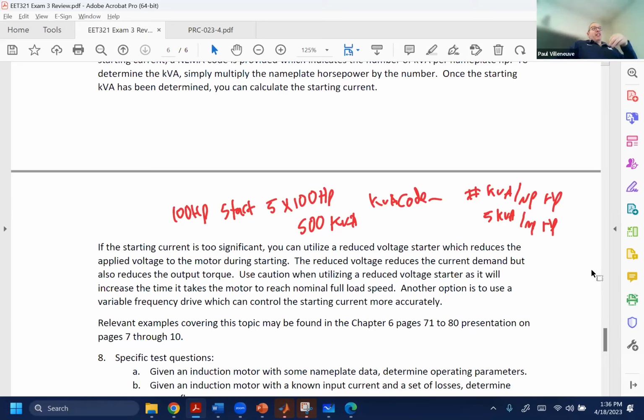And then what they do is they set it in these slots, and they put it into a special oven, vacuum chamber, mixing thing. They heat it up to make sure all the moisture's out. You heat something to 150, 200 degrees, that's well above the dew point. If you give it enough time and pull a vacuum on it, all the water goes away. Then they throw in a liquid resin, an insulating one, and it's warm in there, so this resin flows through.